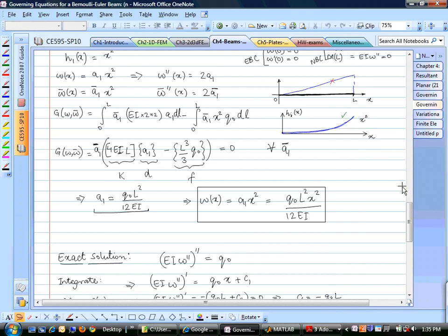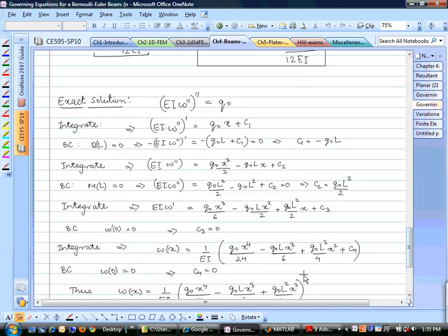So we can add obviously x cube to this term, then we'll have a 2 cross 2 stiffness matrix. If we add x4, then we'll have a 3 cross 3 stiffness matrix, and when we do that, we should recover the exact solution, because we know that anytime we use the Ritz method, if the shape function that we choose has the exact solution in it, then the finite element method or the Ritz method will find that exact solution.